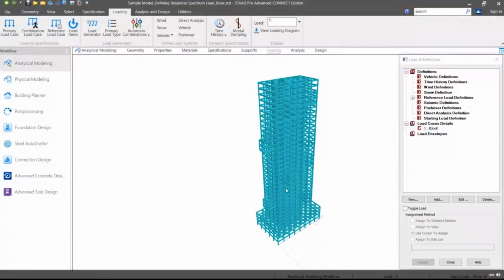Here you can notice that 90% mass participation is achieved in the 11th mode for X direction and the 13th mode for Z direction. Also you can find that the change in mass participation reduces as we go for higher modes. For this model, we can use 15 modes, for which 90% mass participation is achieved for both X and Z direction. Now, in the original model, we can assign the same.